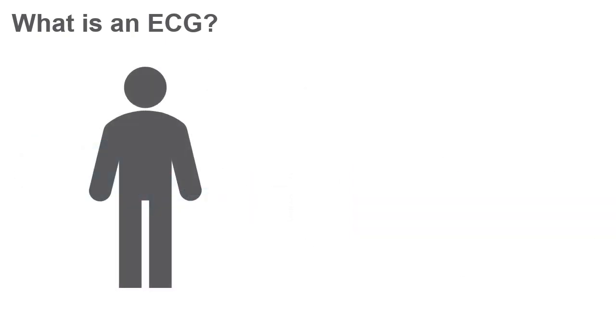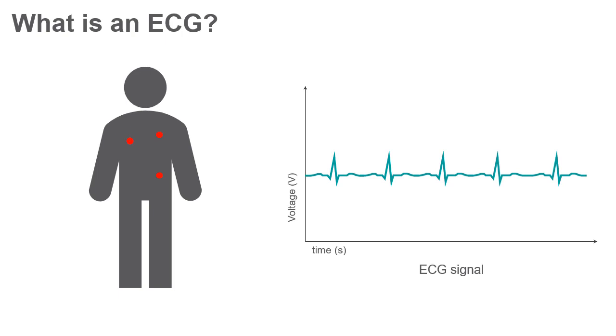ECG measurements are taken by attaching leads to the skin of a patient. Because of the physical constraints of monitoring the heart through the surface of the skin, the detectable signal is incredibly small, and electrical noise can be relatively large. This means that real-world ECG instruments use amplifiers and filters to condition the signal.